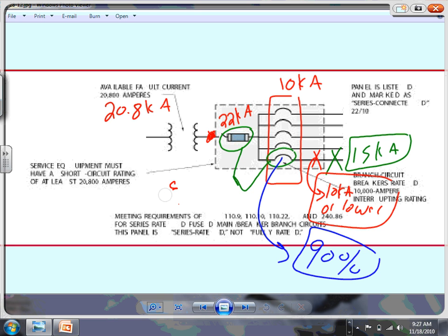What's the alternative? It is to size everything fully rated. What's the advantage of this? Now this is a cheaper product. Now you can have a more affordable, cheaper product, and smaller size. Cheaper product, smaller size. That's the main advantage of series rated.